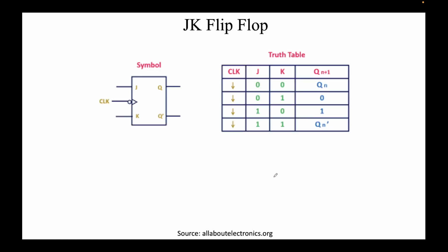When solving any type of problems relating to counters, we need to talk about their building block, which is the JK flip-flop. So on the left you can see the symbol for this flip-flop. J and K are the inputs and Q and Q bar are the outputs, and a clock, and this flip-flop runs on a clock. In this case this flip-flop is edge triggered. You see this triangle, this denotes an edge, and it's a negative edge triggered. So for instance, let's say if the clock is something like this,